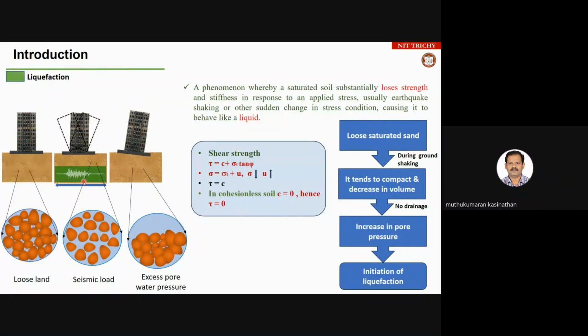And the vibration will propagate through the medium and hit the structure, and the structure is subjected to to and fro motion. Thereby, your supporting soil is subjected to high vibration. During the vibration, which happens instantly, in your saturated soil the pore pressure will build with increasing vibration. To build pore pressure, you do not have enough space to dissipate, so the built pore pressure will try to destroy the soil connection.